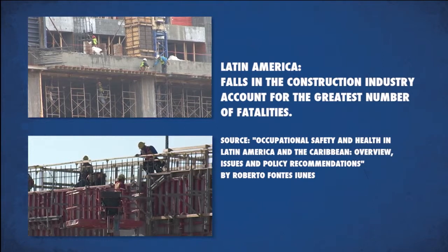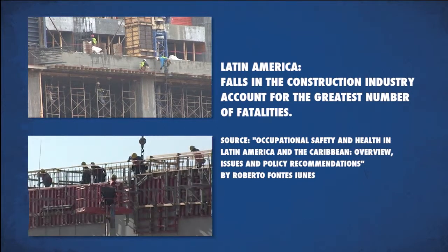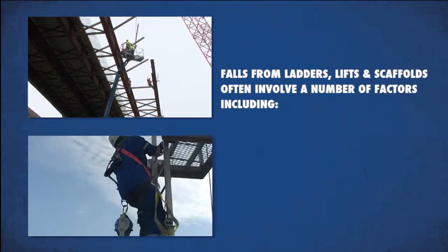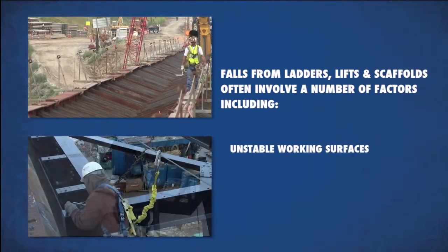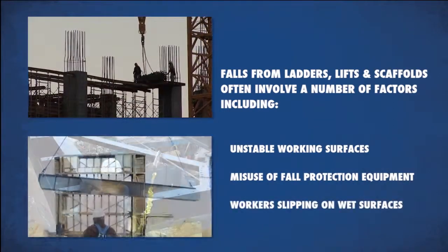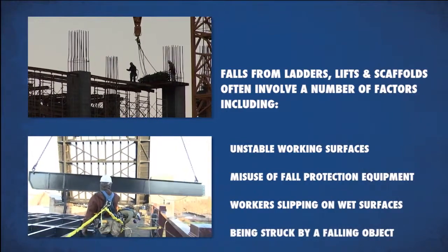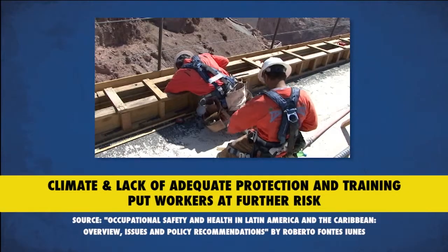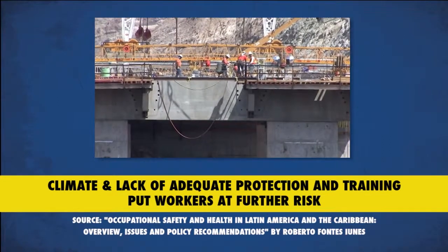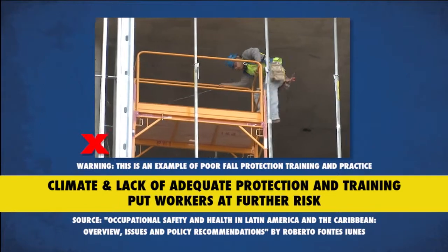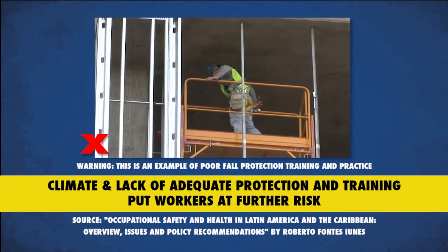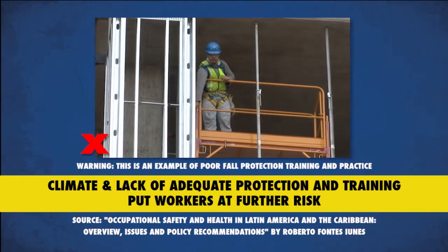And in Latin America, falls in the construction industry account for the greatest number of fatalities. Falls from ladders, lifts, and scaffold often involve a number of factors, including unstable working surfaces, the misuse of fall protection equipment, workers slipping, or being struck by a falling object. While these risks are common to construction in all countries, they are exacerbated by the region's climate, such as heat and humidity, and particularly by the lack of adequate protection and training. This is why it's important to always think about fall protection when you're working at height.